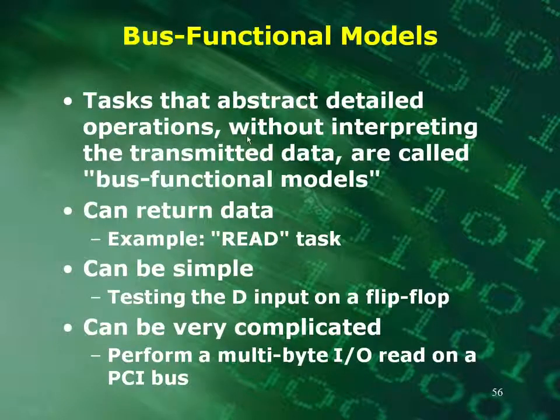Tasks that abstract detailed operations without interpreting the transmitted data are called bus functional models, or BFMs. You could create one to return data, like from a read of something. They can be simple, like we just did with the input on the flip-flop or the inverter, or they can become very complicated, where you're performing multi-byte I/O reads on a PCI bus or something like that.